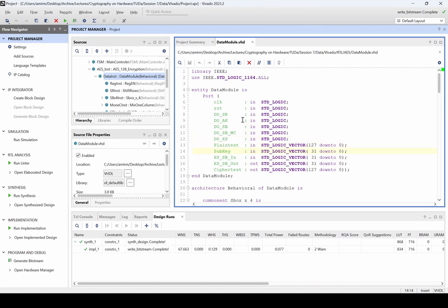Of course, the 32 bits of the subkey are given, and another point is that the output of the key schedule, I mean 32 other outputs, means that the input of the sub bytes for the G function is also given to this module from the key module, and then the output of the Sbox is also provided to be given to the key schedule, for the G function to be computed inside the key schedule.